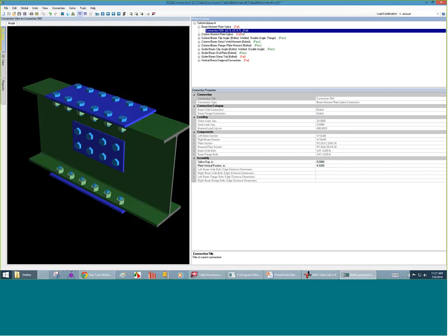So it has failed. And what I can see here is that it's giving me a UC, which indicates unity check, and it's giving me 0.7. Now, a unity check, you always want to be under 1.0. That means it would fit. It would be a passing unity check. So this one is actually indicating a passing unity check, but it fails. So that's a strange one, and you'll see this most commonly.